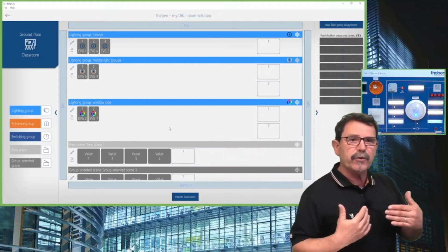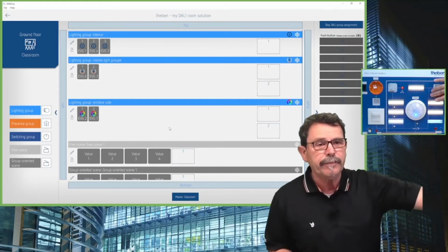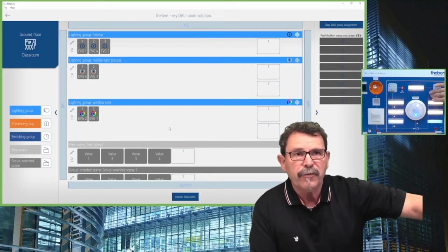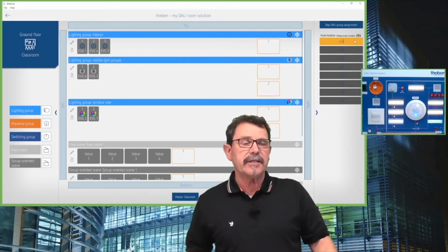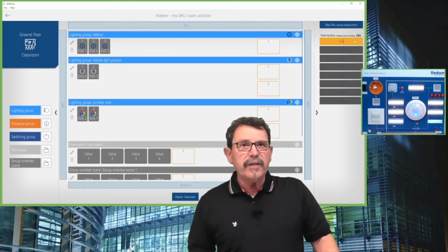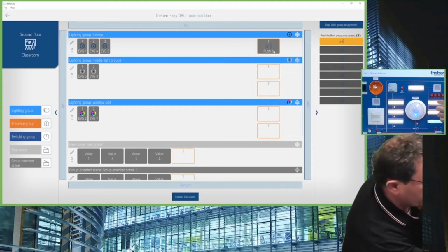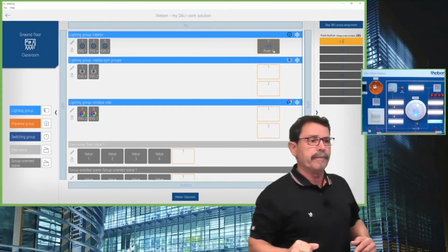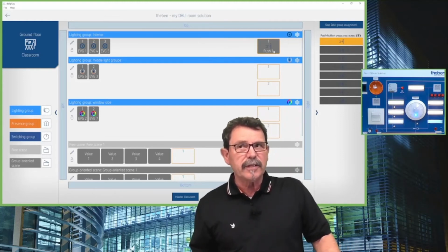So now we have to go another way around. That means we need now to press a push button, which gives me a feedback. So this one, for instance, if I click on that again, now you discover, okay, here on top, this is exactly the push button which is allocated to the DALI interface. And with this push button here, I want to drive, for instance, these lights. So we want to drive this one, this one, and this one. So what does it mean? This one is the central switch and the central dim push button.